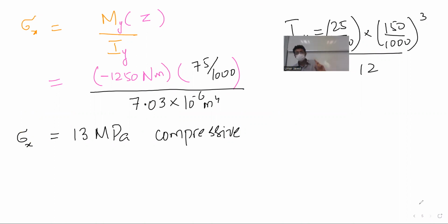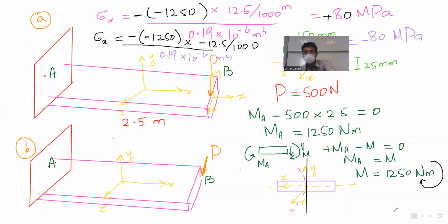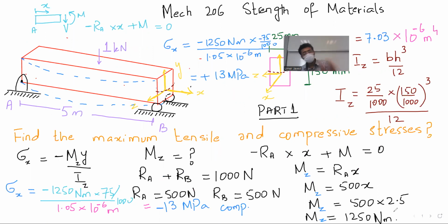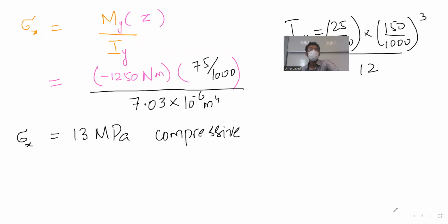So that's why I corrected myself. But please remember that in a very simple formula like this one, it will be stress X equal to minus Mcy over Ic. There are no cons. You have a negative sign here in the formula. But since I changed the problem to a very complicated one, I knew that there cannot be a negative in this new formula that I am making. So I had to remove this.